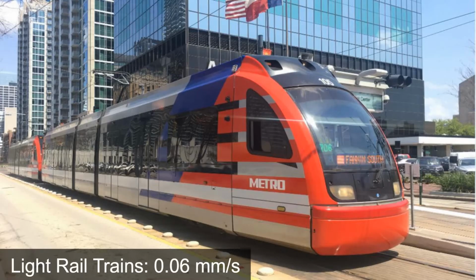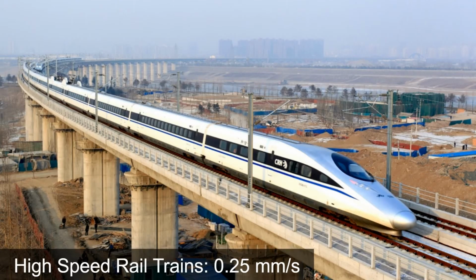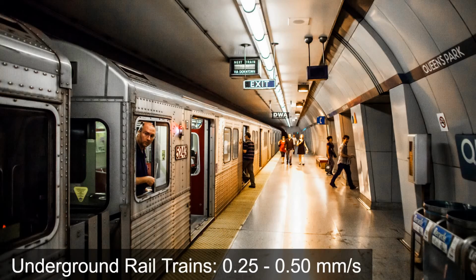Light rail trains have an RMS vibration velocity of around 0.06 millimeters per second. Commuter trains have an RMS vibration velocity of about 0.17 to 0.53 millimeters per second. High-speed rail trains have an RMS vibration velocity of about 0.25 millimeters per second, and underground rail trains have an RMS vibration velocity of about 0.25 to 0.5 millimeters per second.